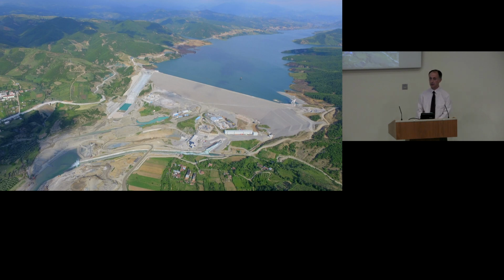The first concern was, would there be voids in this slip mass, and so on and so forth. And so there was a lot of work done on the filtering arrangements. The toe berm, which was going to act as a great lump of weight to hold the thing in place, had to be adequately filtered. So all the filtering arrangements that were necessary for the clay core were repeated when we were putting the toe berm up against it.